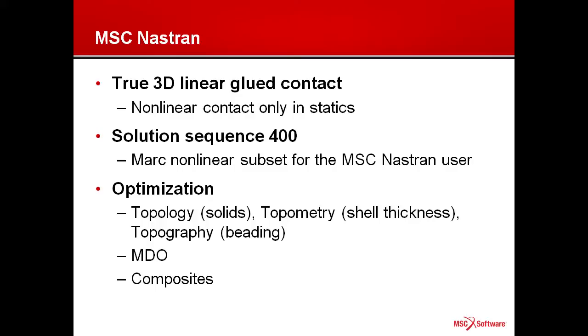We added solution sequence 400, which is a subset of the Marc nonlinear for the Nastran users. So your interface, you're used to Nastran, you're still using it. There was no reason to rewrite the old nonlinear solution, simply because the way they were written was very inefficient. It was better to start from scratch again.